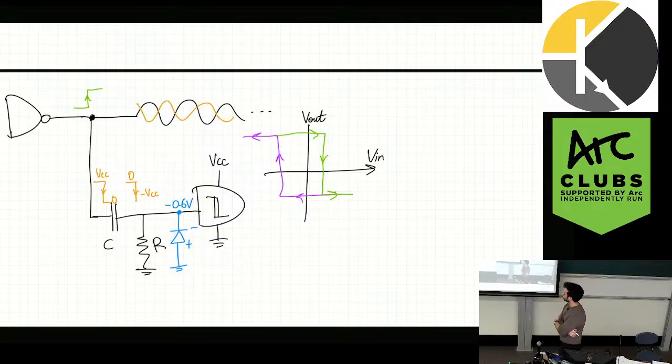Cool. And I'll just mention there are plenty of solutions to this. You could use a latch, you could do the comparator sort of topology. But what is always going to be your best friend in these design questions is an RC time constant filter, right? It is always going to be your best friend. Most of these solutions have an RC filter in them. I think there was one question, I won't spoil it because you're going to get to the past papers yourself. But you're going to find that it's a common theme for detection circuits.